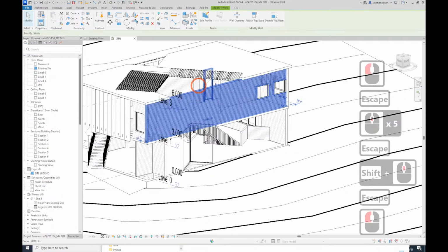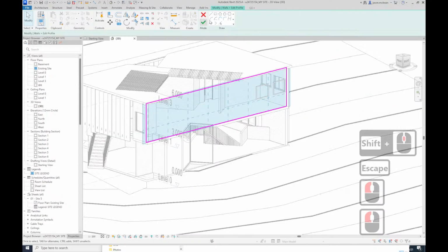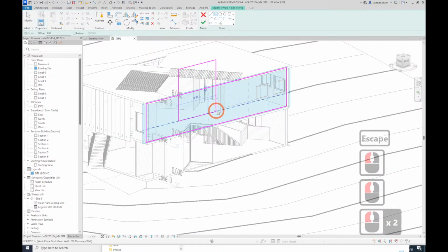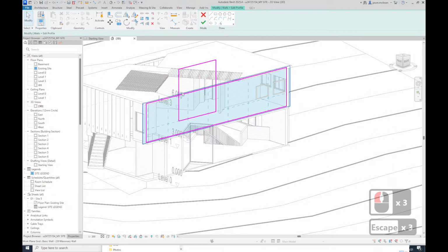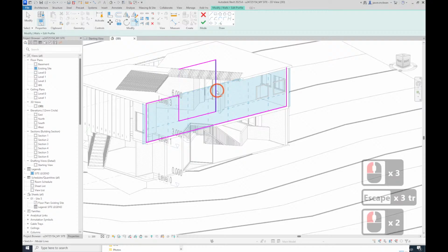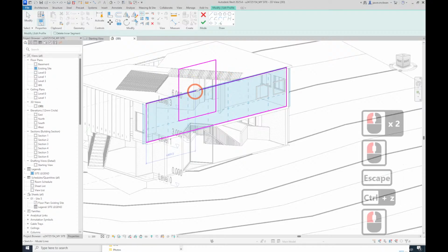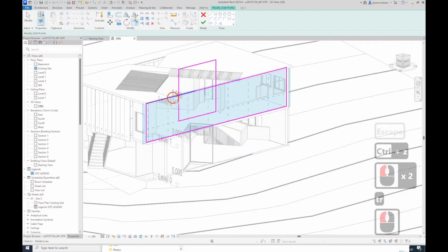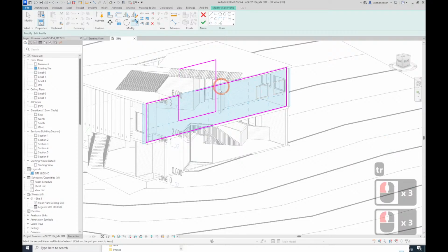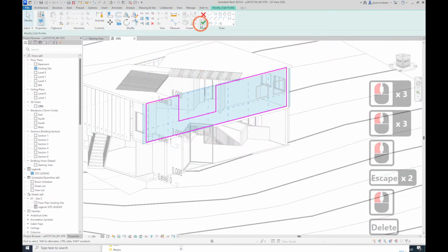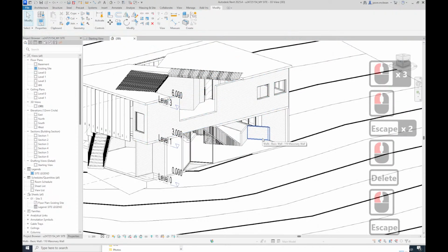Now, with walls, you can edit their profile, so you can cut away sections that you don't want to see. Very easy. Trim. You can also use open. Oh, don't do that. You must split that line. That line's very important. So trim. I'll explain why you want to do this, because otherwise your floors don't work well. Voila.